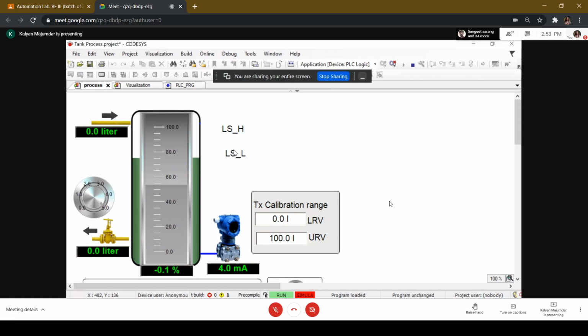So physically in the process, you would have two tanks, one on the top, one on the bottom. You would have an outflow line. The amount of liquid outflowing we do not know, so that is controlled by this particular knob. Inflow rate, I'll come to this. The inflow rate depends, obviously you can guess, upon the pump. And we have two level switches. Additionally, we can also have a level transmitter. Level transmitter gives you 4 to 20 milliampere current. Then how do you map the level transmitter to level?